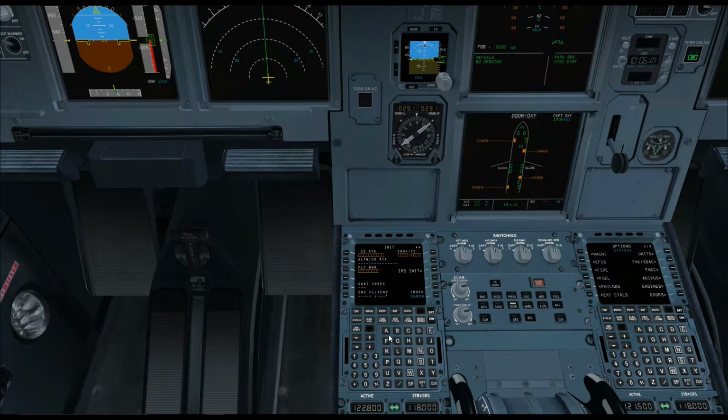We can therefore select the initial page, and the FS Labs A320X has a fantastic feature which allows you to download information from the AOC via ACARS as you would in the real airplane, and you can set all of this information if required individually. So the from/to would be the ICAO codes for our departure, which in our case is Echo Golf Golf Delta for Bristol, / destination ICAO code, and Dubrovnik is Lima Delta Delta Uniform, so that will be ours.